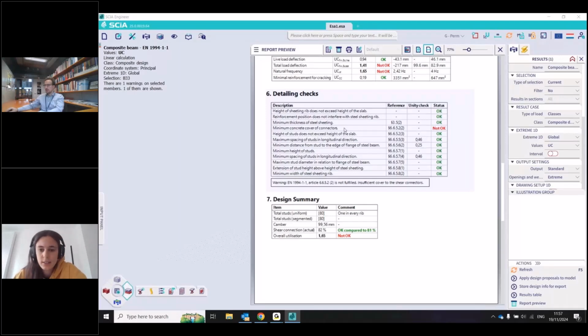It's something that I didn't look into earlier in the settings. Or you can also choose to ignore this check. For example, we can consider that actually on top of our concrete slab, there is still a thick layer of the road that the cars will drive over, and therefore the concrete cover will be fine. I can also in the settings choose to deactivate this check.